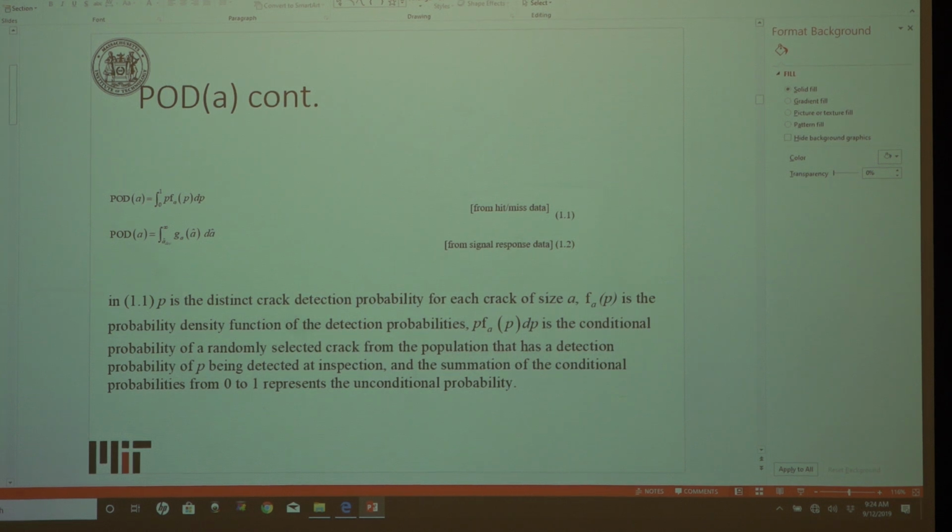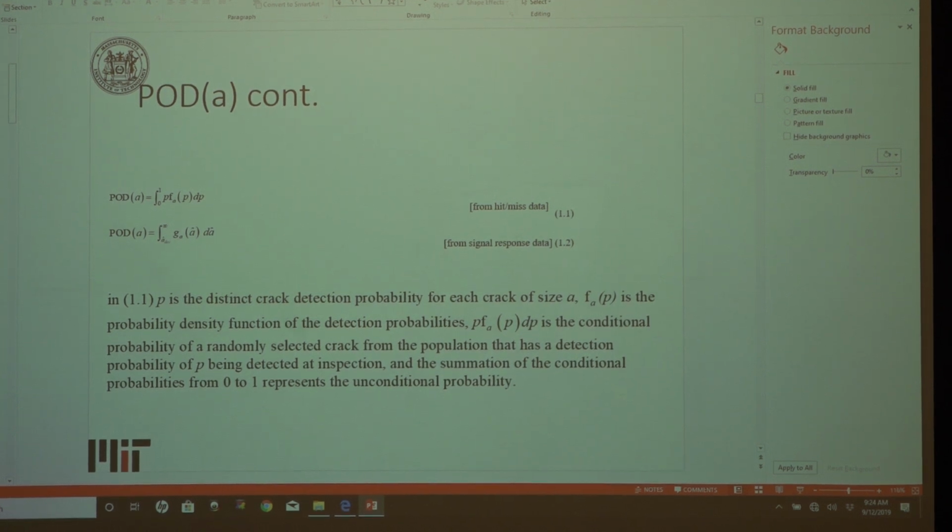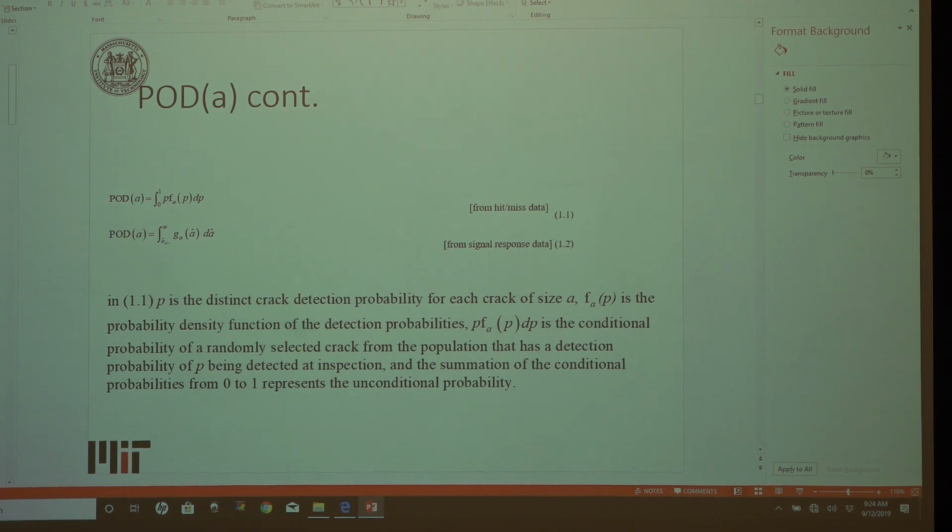For an original equipment manufacturer, the person who actually makes the component, based on their designs they'll generally have an idea of where the highest stress locations will be, whether it's near a weld, a double curvature, or a taper. That's dependent on the component. So being the person who manufactures the component, you generally know where the weak spots in the design are.